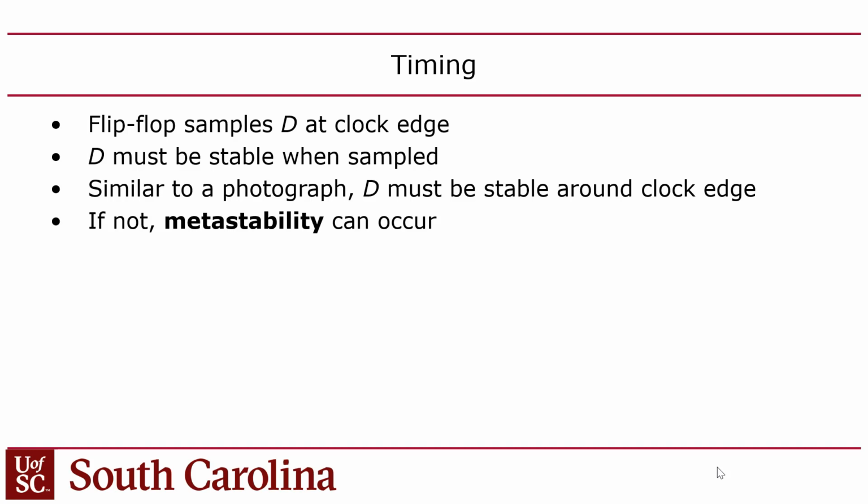For example, your instruction RAM is the starting point, right, of say your execute stage, and then the ending point is the register file, right? Or you also have a chance, like for the CSRRW instruction, where your starting point is the instruction, the data passes through the register file, and then you may end up in the register that drives the hex displays, right?